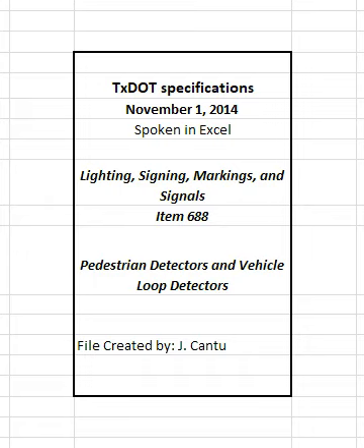Twist the wire from the loop to the ground box a minimum of 5 turns per foot. When only one pair of wires is in a saw cut, it need not be twisted while in the saw cut. Do not splice loop wire in the loop or in the run to the ground box.